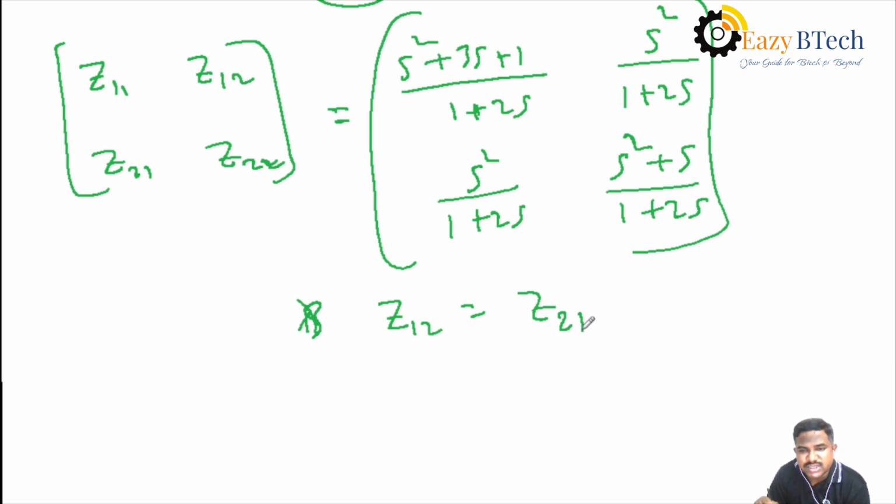In this way, you have to find the given network in transformed variables. That is, you have to apply Laplace transformation for every element, R, L or C. Then after that, apply KVL or KCL. You can derive the equations in the form of standard equations of two-port network parameters. Then find the required parameters in terms of S, that is, the Laplace transformation terms.